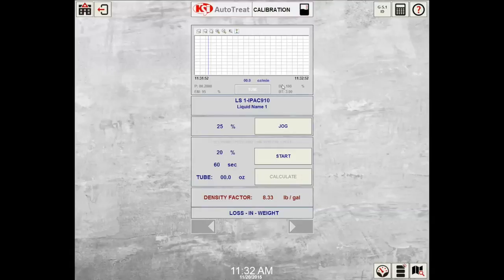The boost amount is the value that defines what percent of the liquid delivery target the pump will boost at the beginning of the run. This value allows the system to turn the pump on as close to the target amount as possible. So for this example, I have it set at 100%, so it boosts right to that target amount off the start. Right underneath that is the boost time, which looks at how long it will run. So 3 seconds in this instance at 100%.